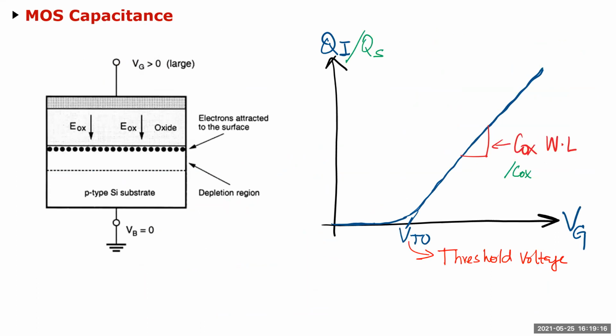Okay, before I show you the other ones, just quickly the MOS capacitance. In IC design, you're always just using MOS capacitance for everything, as a load or as a capacitor, but it's actually a very linear capacitor after the channel turns on. You can see from this graph, as the voltage is increasing, the channel doesn't form. Obviously, we have been saying that the channel doesn't form till VT0, but in reality, the channel turns on kind of before that.